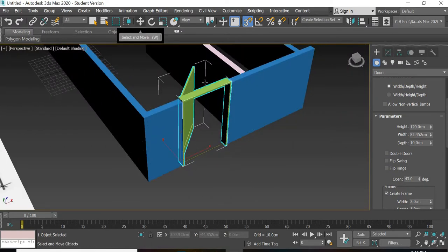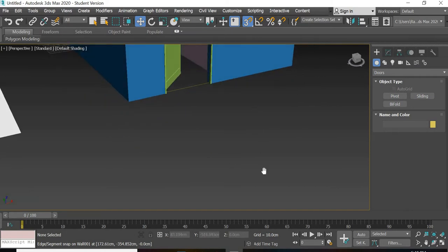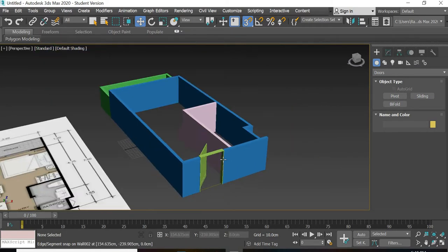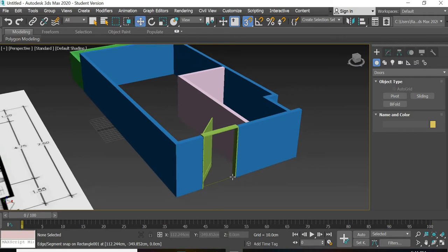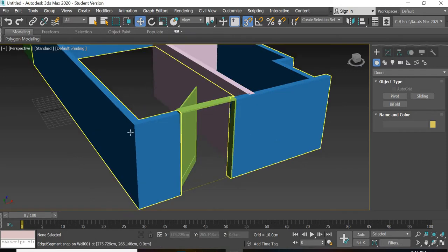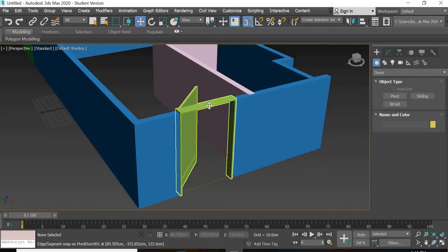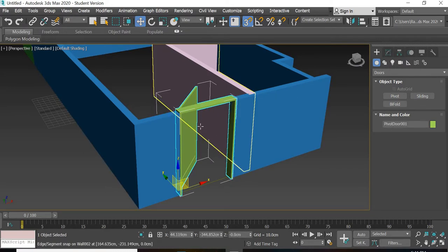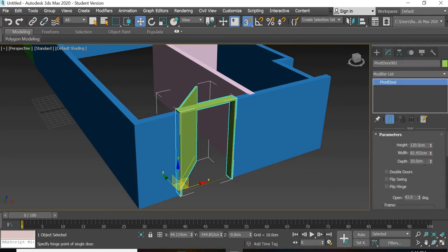Alright, so we don't have to create the door opening when you're modeling your walls. If you're using the wall element, this will not happen with a box, it will only happen with the wall, that you can insert a door or a window and an opening is created. Now in this case, we can decide the depth.